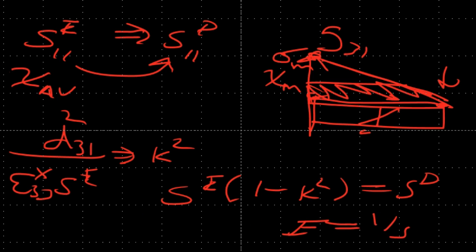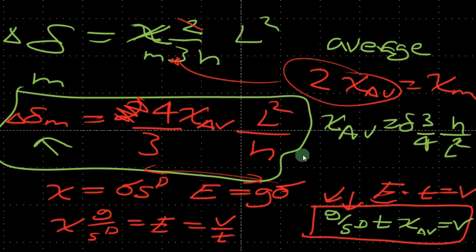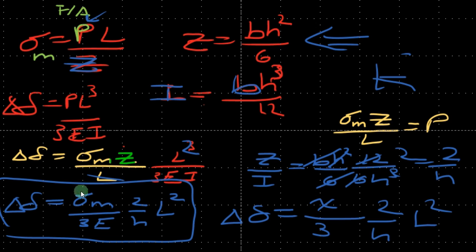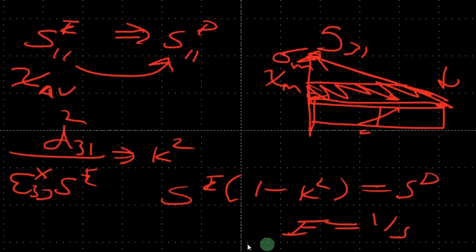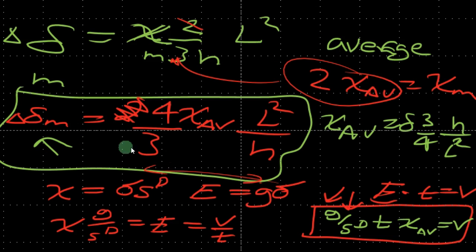And remember, usually when we're talking about Young's modulus it is 1 over S. For piezos, we usually use S. Back here, we had elastic modulus as E. That's like the inverse. This is like stiffness, and compliance is like softness, you could say. So it's 1 over that. That's something not to get confused about. So we use this equation here. Let's keep going and finish it up.